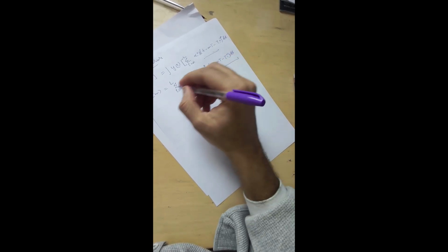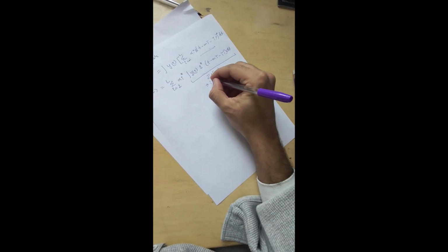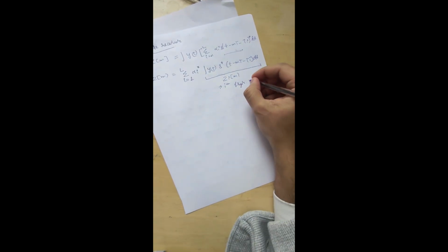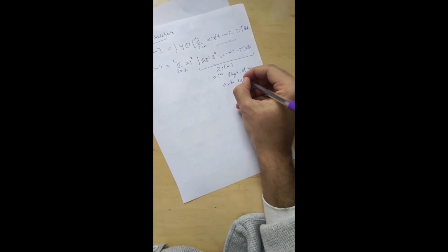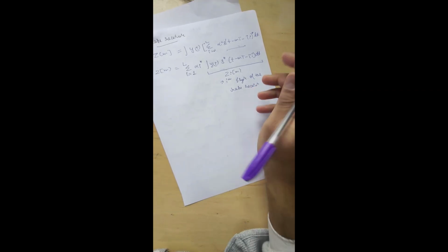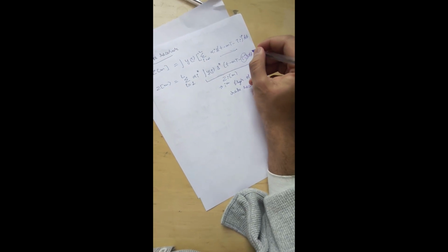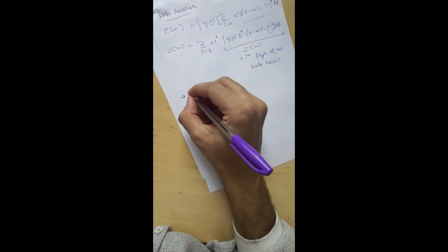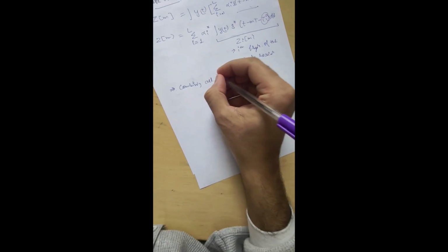So each integral zi represents a single finger, or the ith finger, of the Rake receiver, correlating the input with a specific delay tau i. And the final step is actually combining all the fingers.